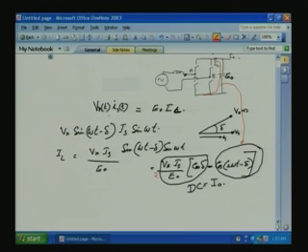So, once again, this is the input power, sinusoidal fundamental voltage into sinusoidal current. This is the output power from the converter. Now, VRT from this definition is VR sin omega t minus delta into Is sin omega t. So, the IL which is coming from here, you will get this equation, but when you convert to this one, there has to be a 2, because we are converting sin A sin B to cos.